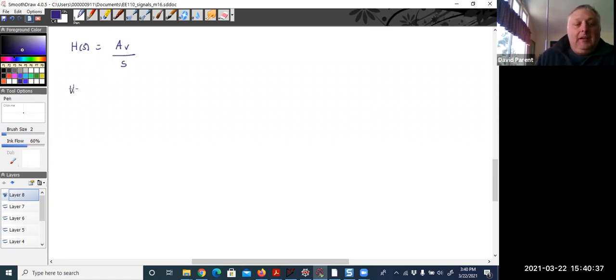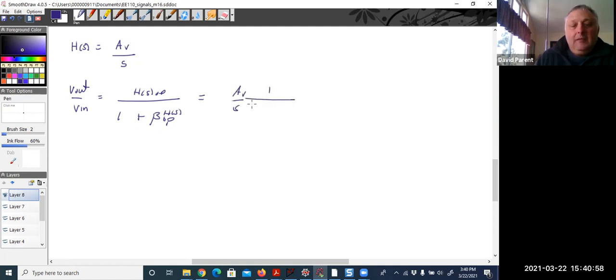Well, I'm going to go back and just rather than rederive it, Vout over Vin equals H(s) of the op amp over 1 plus beta times H(s) of the op amp. And so I get A_V divided by s over 1 plus beta A_V divided by s, multiply through by s.